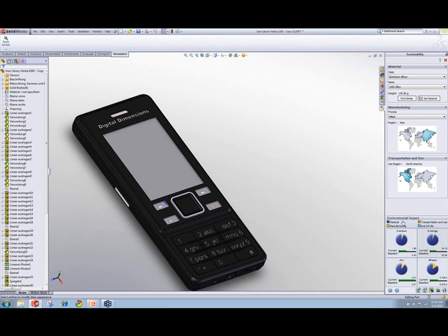Now from that, SOLIDWORKS in real time will calculate an environmental impact. These are the 4 factors that we've talked about previously. For carbon footprint, we have 1.96. Energy in megajoules, 24.19, air quality 0.01, and 4.72 e to the 4 for water usage or eutrophication.